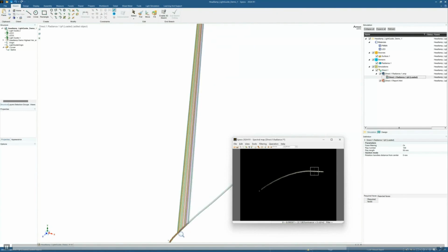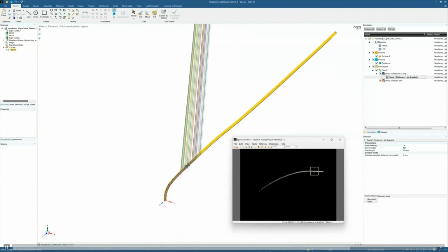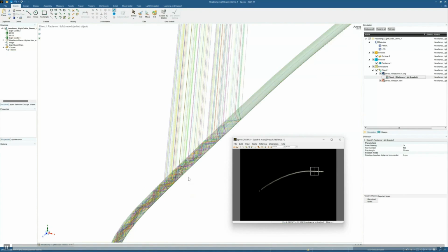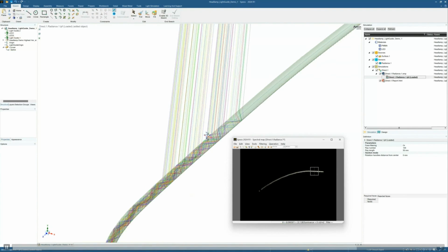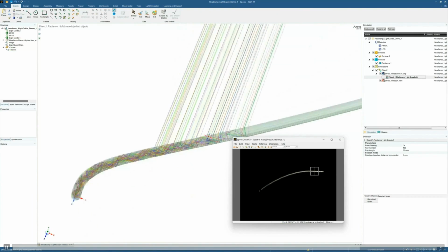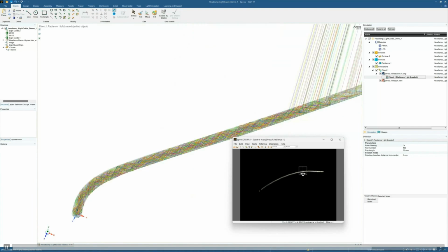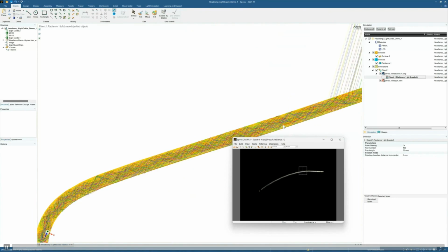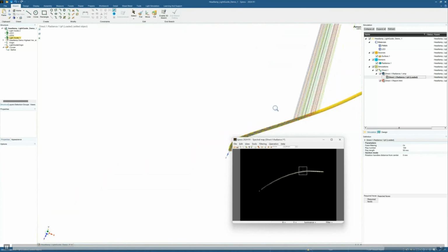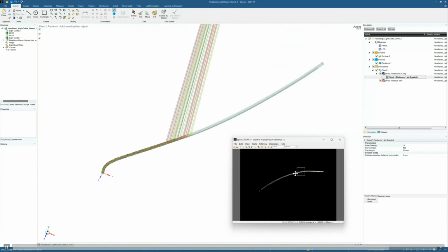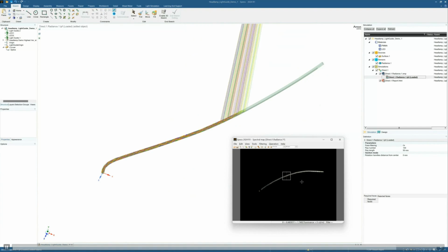All of the light that's inside of that square on that LPF file, we can see how it's getting ray traced through the system from the source. As we move that square along, the rays are going to follow it. Now, if I made that box really big and I made the entire light guide inside of that box, you would see the output rays coming out all along the entire length. I'm just keeping the box small for this purpose.